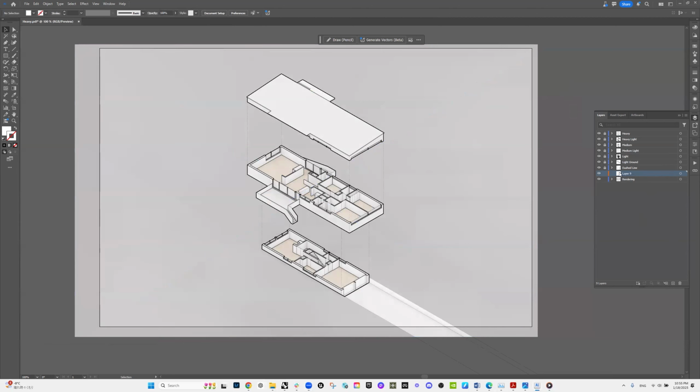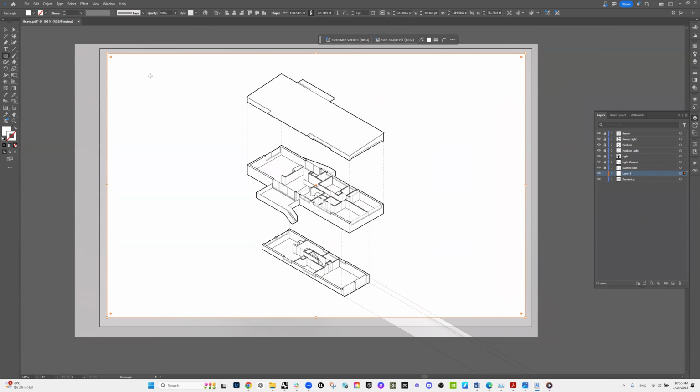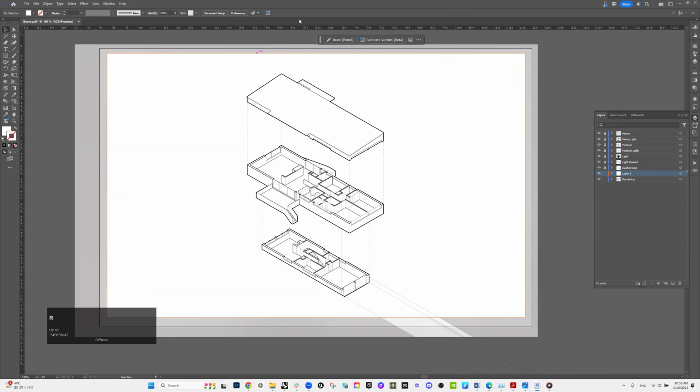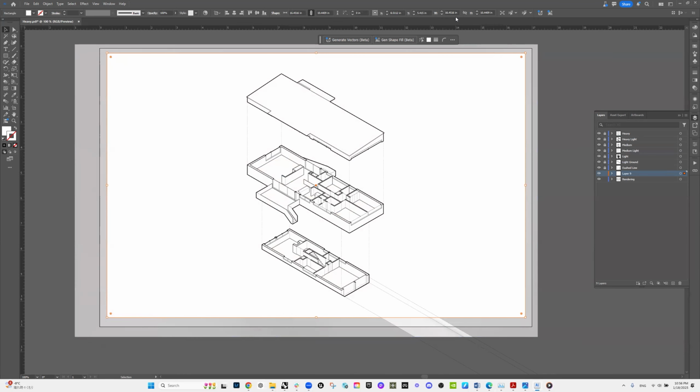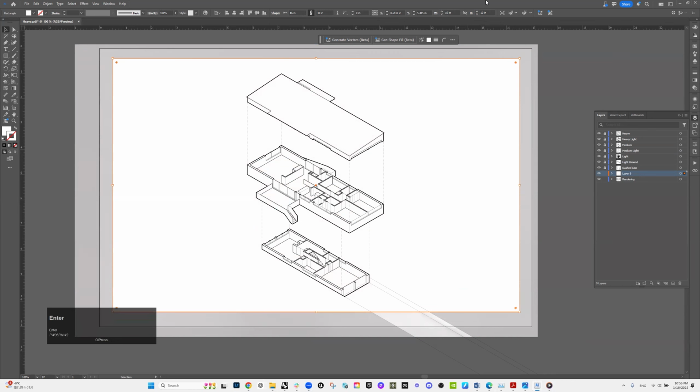Uh, but yeah, so that's how you can create this. And of course, I can create a new layer and then create this rectangle of 16 by 10 like last time. So Control Alt to bring this ruler out. I'm gonna change that to inches and select this to change the size of this rectangle to 16 by 11, 10 over here.